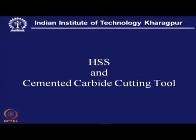So, here we have HSS and cemented carbide. Obviously, for the reason known to us, for HSS we have to restrict the deposition temperature well within 500, and for carbide it can go around 1000 without having much problem, and that is why we have PVD coating and CVD coating.